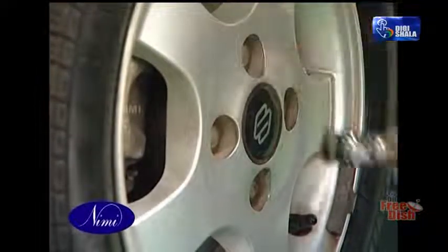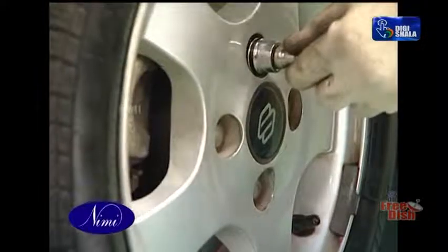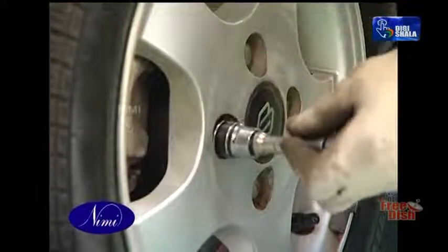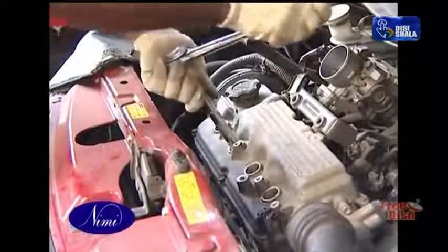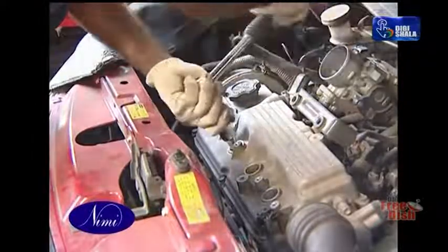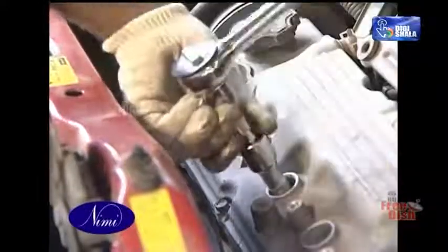Torquing to a value less than specified results in leaks, looseness, relative movements of parts, vibration, etc. Over-torquing results in damage to threads or fasteners strained to the breaking points. Torque values are based on type of joint, internal pressure to be sealed, vibrations, fastener material, etc., and are specified by all vehicle manufacturers.